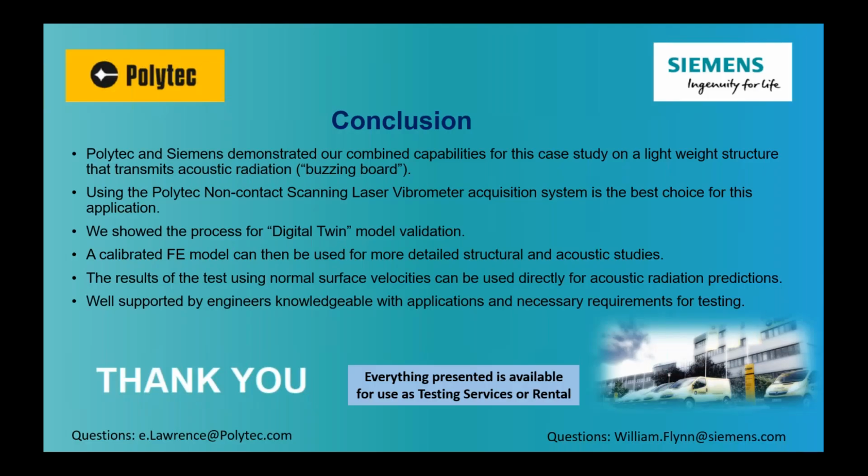And so in conclusion to the presentation today, Polytec and Siemens collaborated on this test, showing the measurements with a laser vibrometer of the buzzing board, and how those measurements could be used for not only the structural correlation and model updating, but also for acoustic simulation prediction. And we can do that with either the direct measurements or through an updated finite element model or digital twin. So the results of the test using normal surface velocities can be used directly.